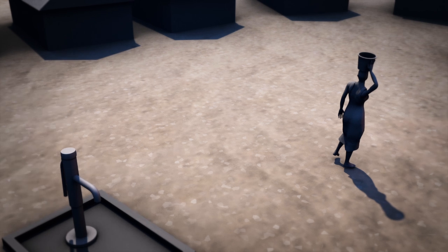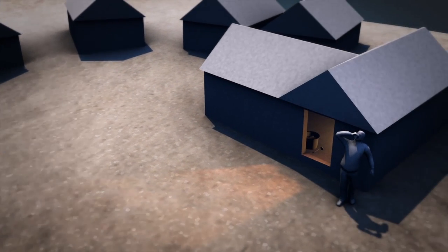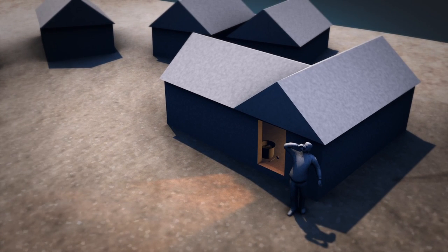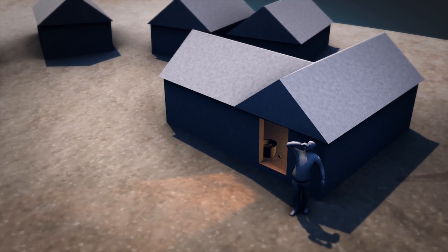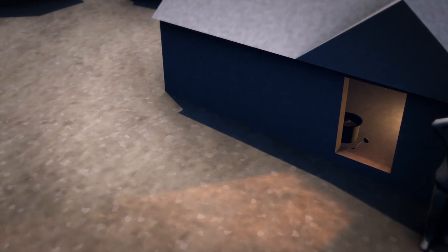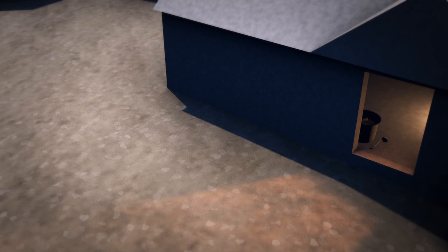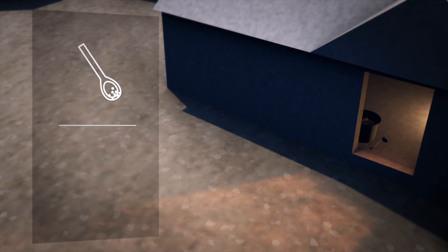Once the water is taken to the household, it is often transferred to another container and may be stored unhygienically in open containers or on the floor where children and animals can introduce pathogens. Point-of-use water treatment at this stage offers the possibility of inactivating pathogens introduced at earlier points in the water chain. But even after storage, contamination possibilities exist.